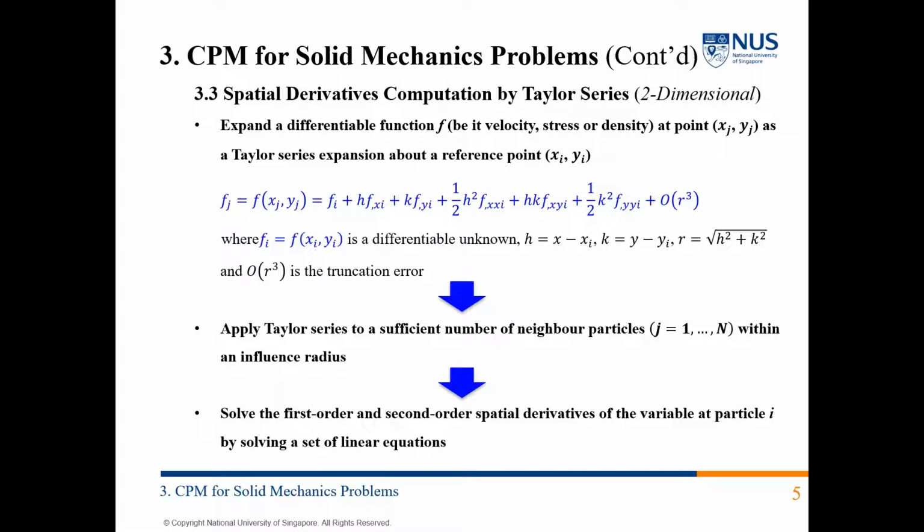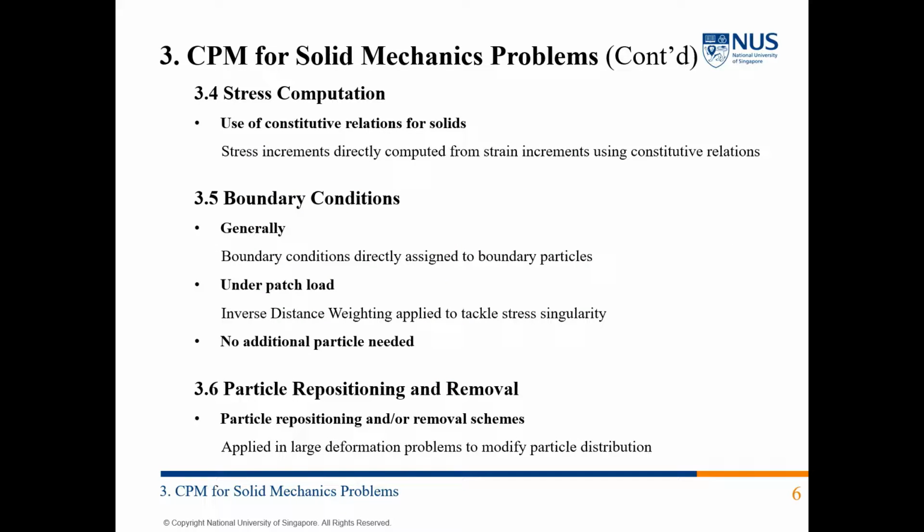The expansion of a differentiable function f about a reference point I can be written in the equation here. Applying Taylor series to a sufficient number of neighbor particles within an influence radius of the reference particle I, we can get a set of linear equations, solving which the spatial derivatives at I can be obtained. The stress increments are directly computed using the constitutive relations for solids.